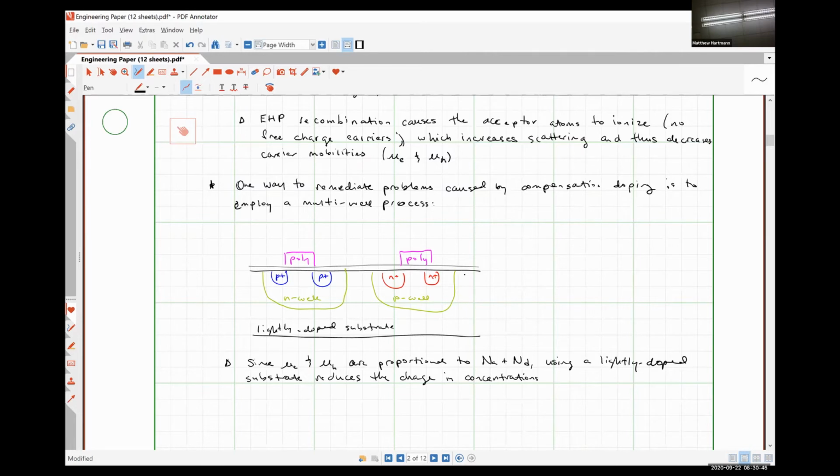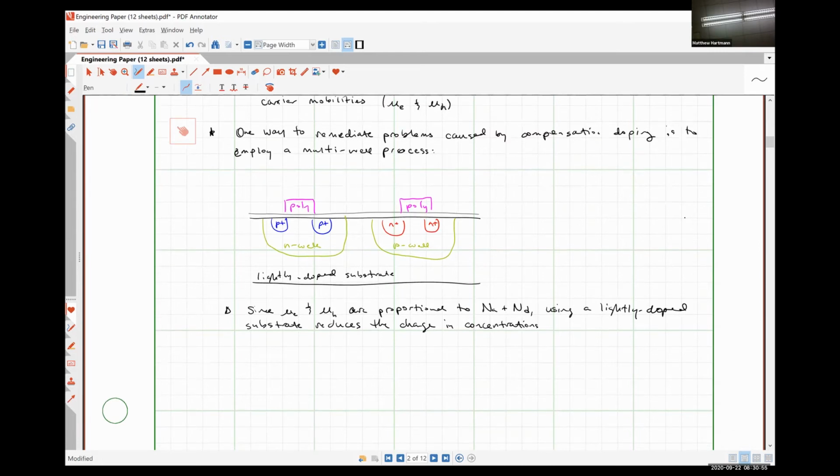Alrighty. So we've talked about how wells are used in the creation of transistors. Now let's talk about another very common use. And we're going to talk about specifically N-well resistors, although we could make a P-well resistor. No problem with that whatsoever. But we're talking about N-well resistors because pretty much from here on out, we're going to be assuming that our substrate is doped p-type.